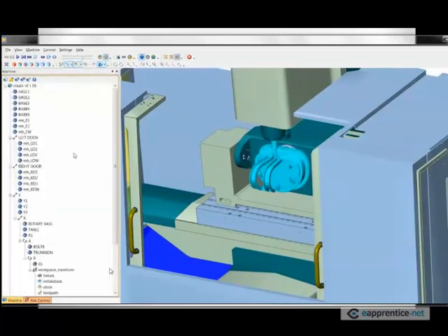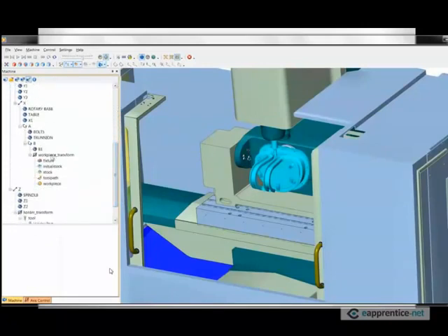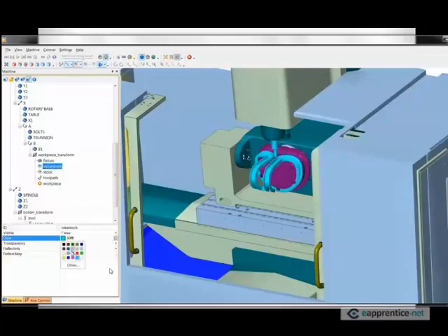So what I want to do next is go back and change the colors of my, go to edit machine here, and this allows me to go to this workpiece transform, set my fixture. So every time the fixture comes in, and this dynamically comes in from the Mastercam file, it will be the color I choose here, the initial stock. Right now I'm not running material removal because I'm just running a motion simulation. But I'm setting all the settings so I want my part to be that color.